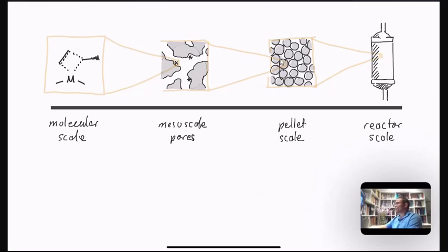And our ultimate goal, of course, once we have the rate on a per pellet basis and we have the number of pellets in the packing per unit volume, then we can begin to put these descriptions into our reactor scale models and employ the machinery that you all are probably fairly familiar with from undergraduate work. Notice how at every step we build a model of what's happening at the small scale and then really embed it consistently into the balance equations for processes happening at the larger scale. This is a really useful way of exploiting natural time and length scale separations that's quite common in kinetics.